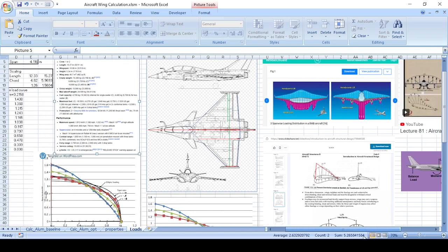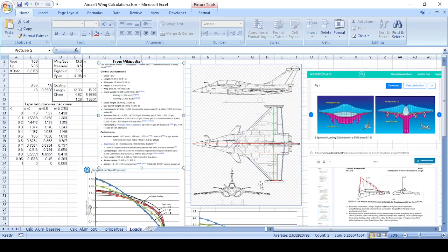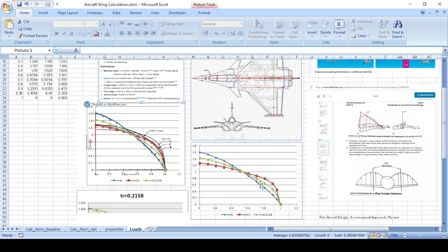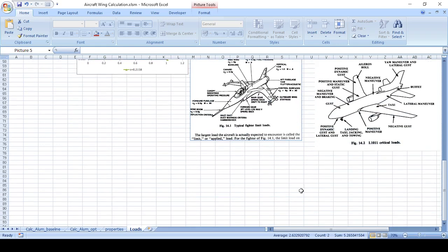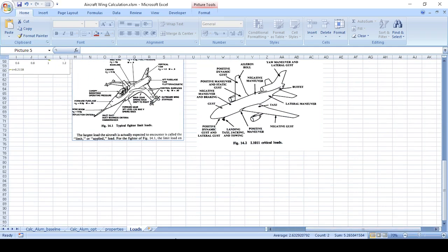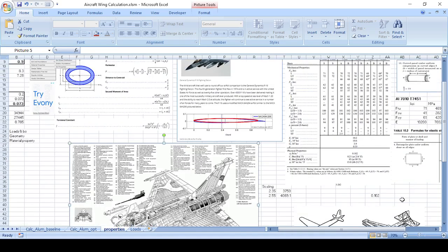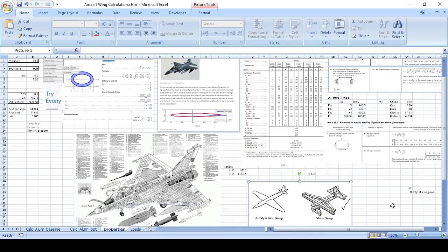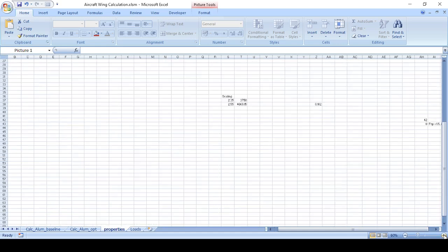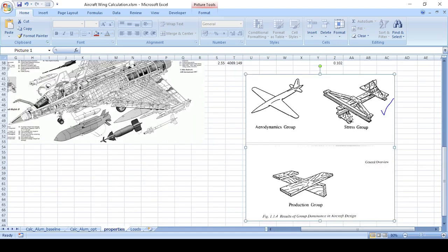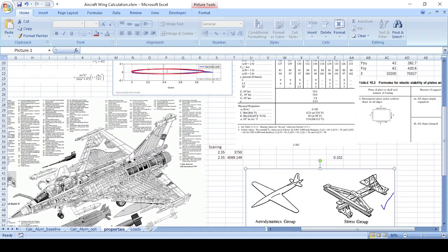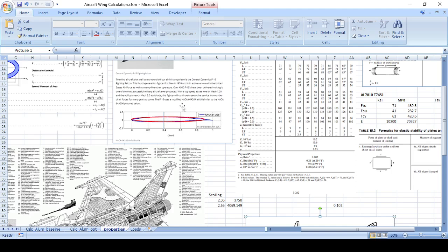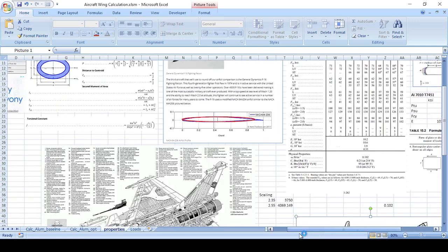In here, I've not actually considered wing torsion, so I've just really considered the wing bending and shear force. For this exercise, like I said, I'm using the I-beam equation. So like I said earlier, I've used this I-beam assumption, which means that my spar is taking my shear load, and my skin is going to be taking my wing bending. So for that, I need a moment of inertia for my aerofoil shape for my wing skin, and I've approximated it as an oval.